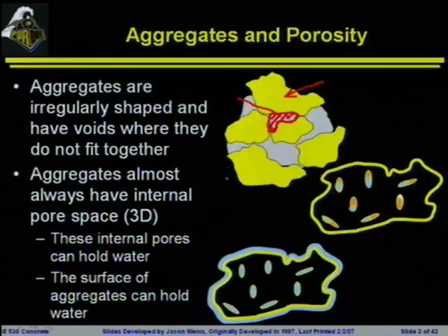The second type of porosity that we're dealing with here is shown in my own very creative version of an aggregate, and inside of that aggregate I have these pores. In this picture those pores are partially filled with water, which I've drawn here in aqua, and then they're partially empty. Now, this is not a very accurate description of what the water distribution actually looks like in those pores, because we would typically empty out a hole in the middle of the porosity first, because the water likes to stick to the pores. But it illustrates that there will be some water and some air in the system if it's not completely saturated.